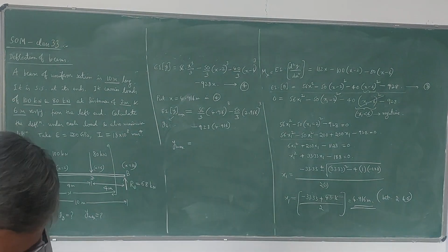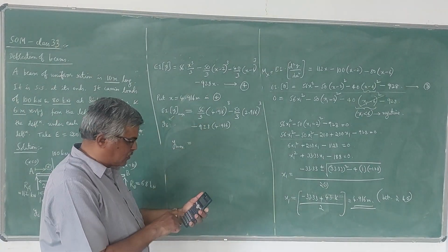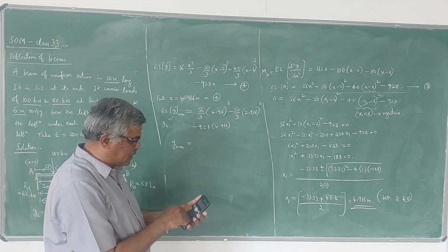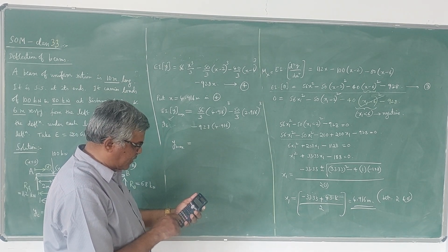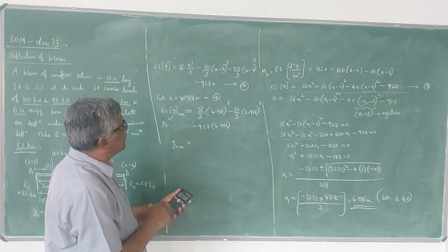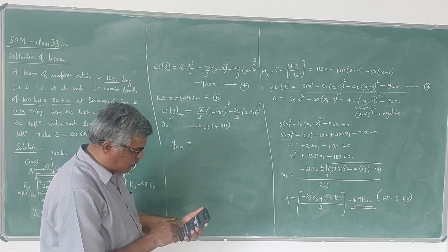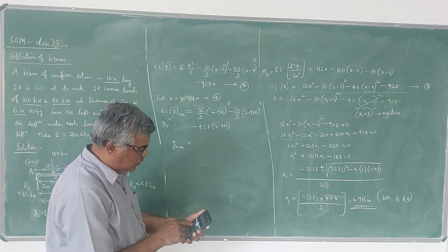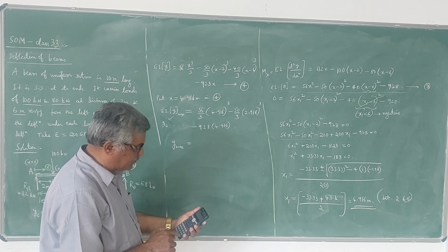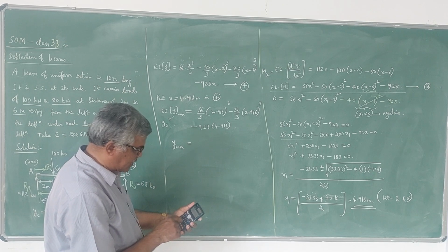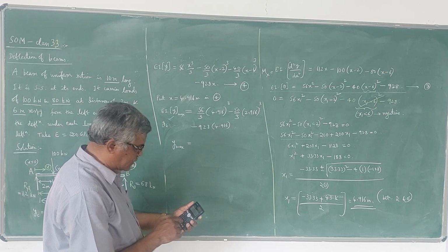So therefore y max is equal to, let me write that. I have to simplify the RHS terms now. So I will take 4.916 whole cube into 56 divided by 3, that is the first term. The second term is minus 2.916 whole cube into 50 divided by 3. The third term is minus 928 into 4.916. So the value becomes now